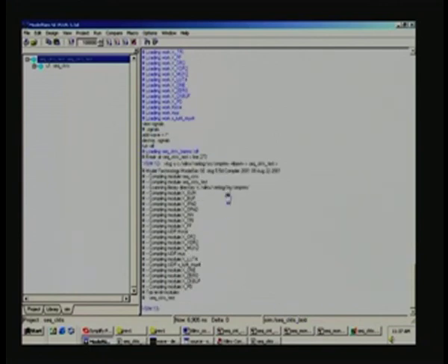So, this is what you have to bear in mind, and now let us see the ModelSim window, that is here. The first step is compilation, which has already been keyed in here: vlog -y, all that we have already seen, and sequential_circuits_test.v. Let us execute this, just give a return. It has done the compilation. During the compilation it reports compiling module X_BUFF, then IPAD, OPAD, invert, tri-state buffer, flip flops, OR gate, exclusive OR, MUX, and so on.